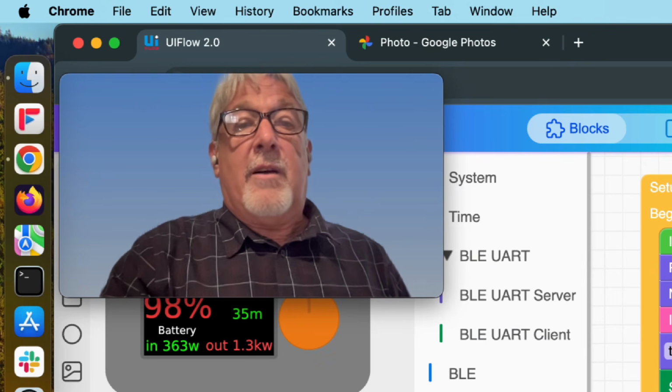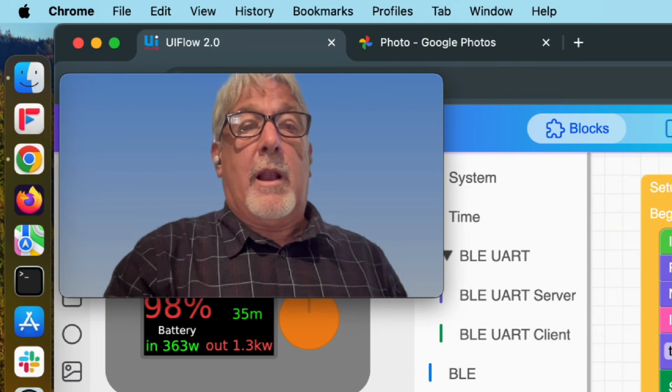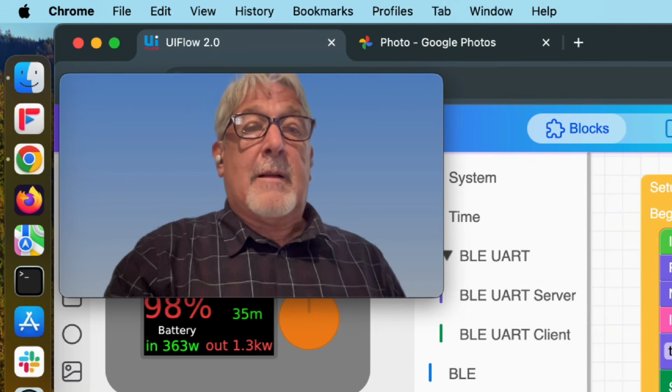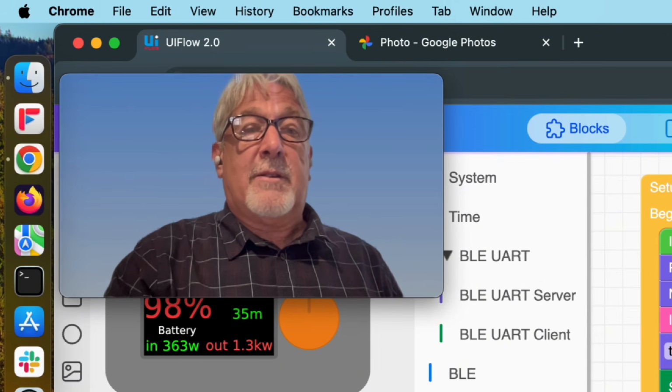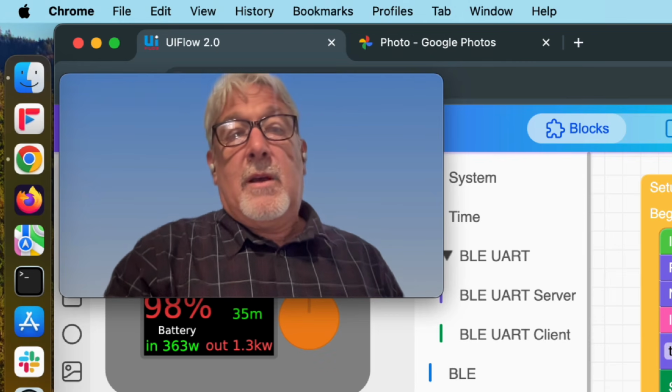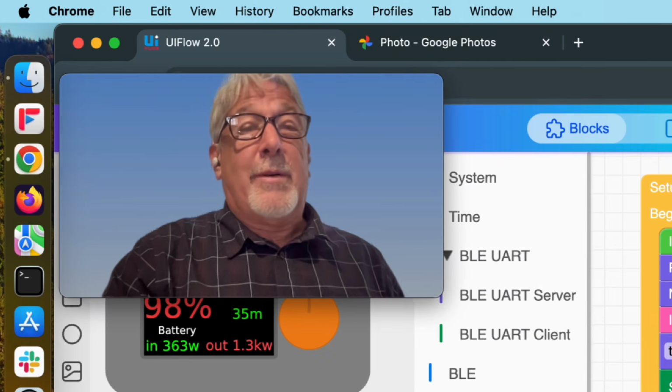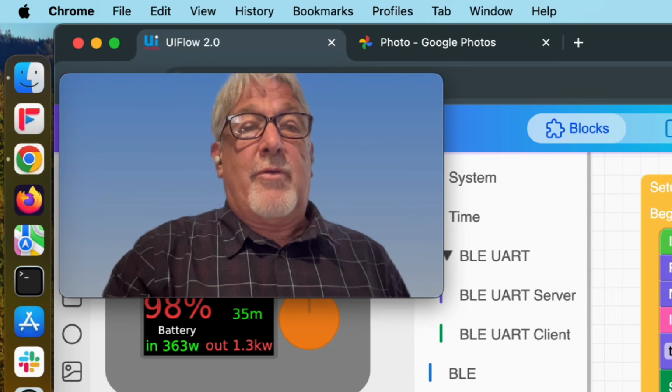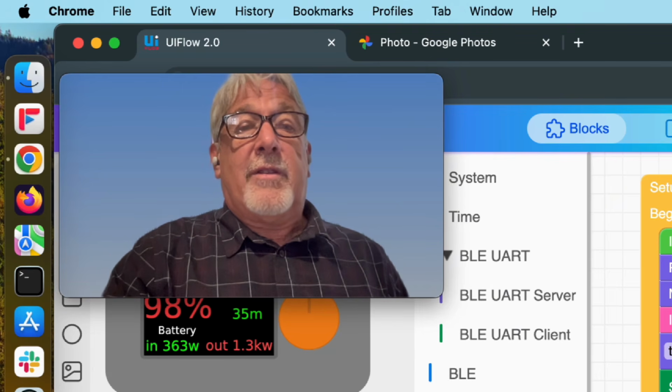So the sails are all controlled by one line. So it has balanced rotating mast sails. So it's basically very similar to a small radio control boat in a pond with one servo controlling the sail angles. And I can control every point of sail with one line.